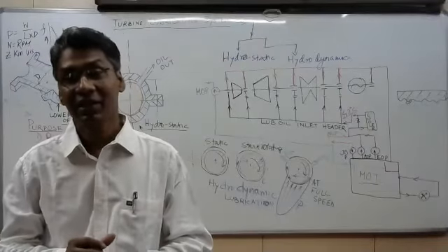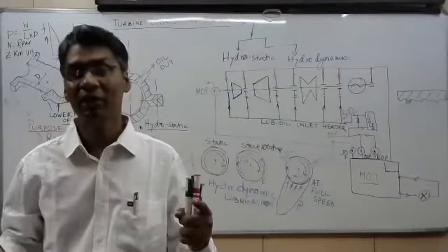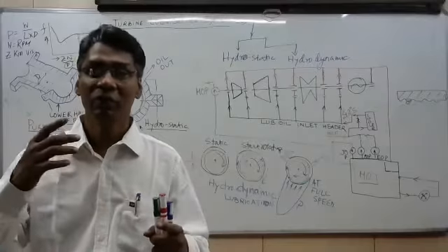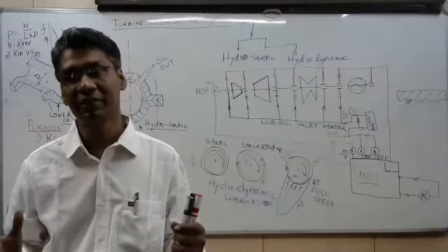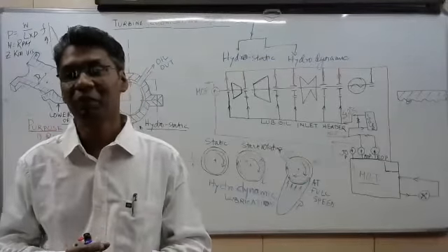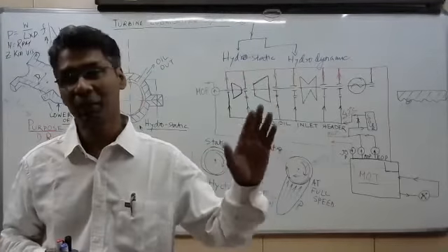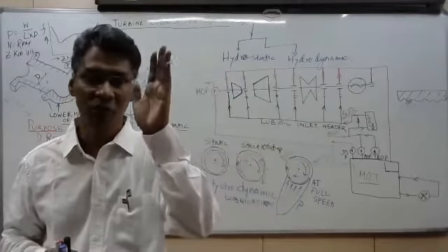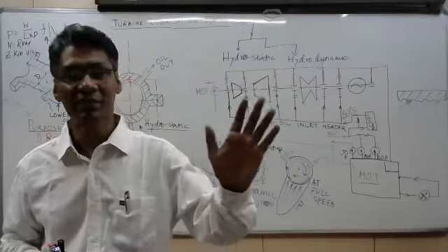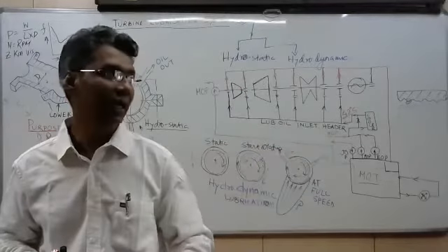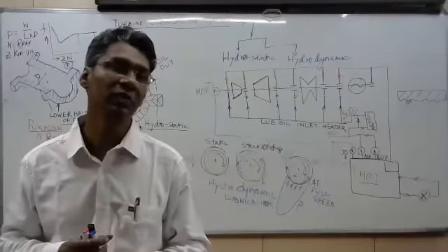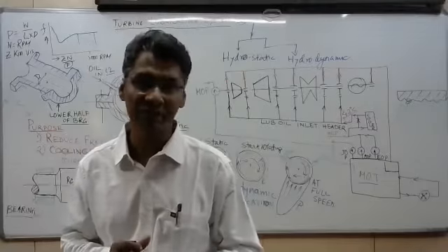It is allowing no metal to metal contact, and minimum frictional loss is achieved through this hydrodynamic system. By cutting off this oil, you cannot test it. It has already happened in a power plant, the damage. If by any means the oil supply is prevented, the accident will be huge. There will be casualties also. Next.